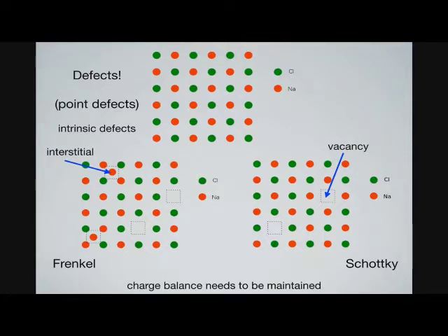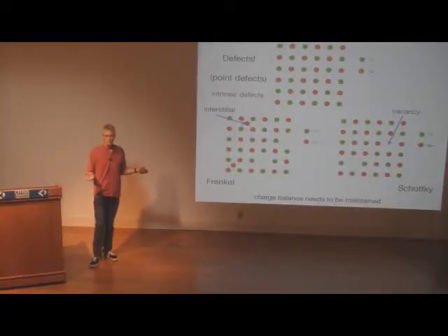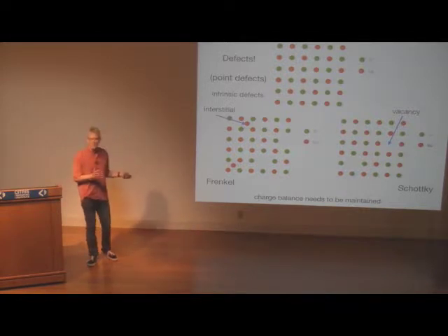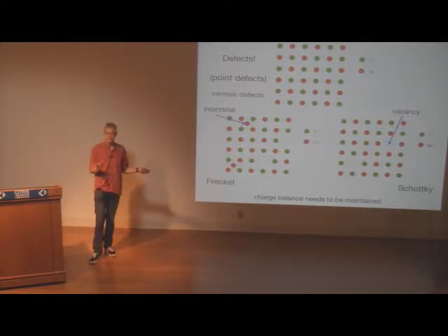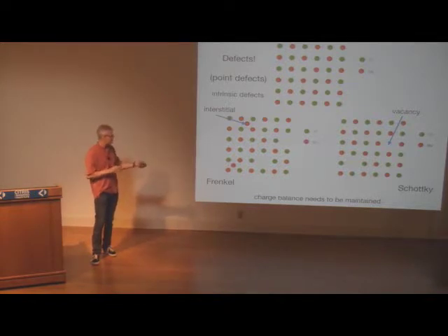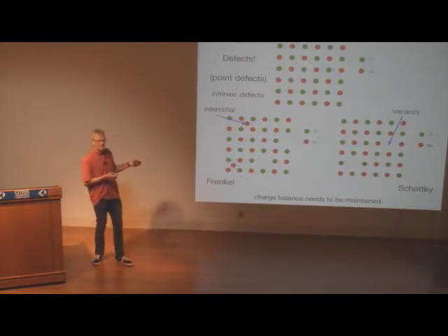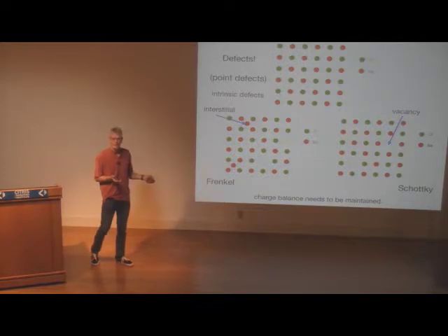And it's really interesting already here, you can start wondering what the effect of pressure is, for example. Those are things that I don't know that we actually understand that perfectly, right? If you want to create interstitials, there may be a penalty due to pressure, which you don't really have at 1 atmosphere. But at higher pressures, interstitials might not be very favorable because, again, you distort the lattice, you have to blow it up a bit. So energetically, it might be unfavorable to have interstitial defects rather than vacancies.